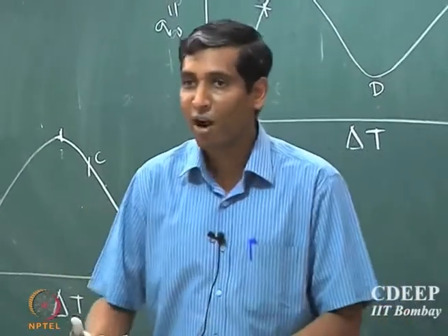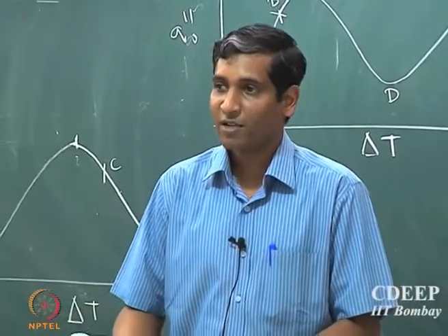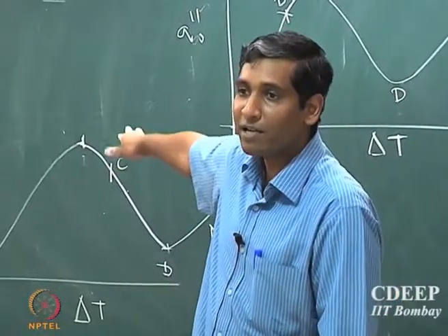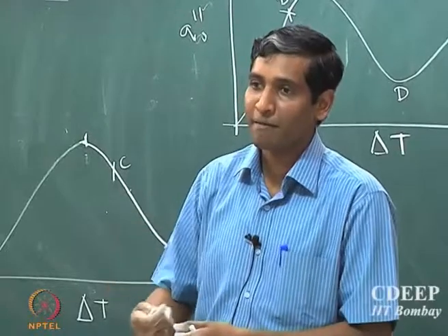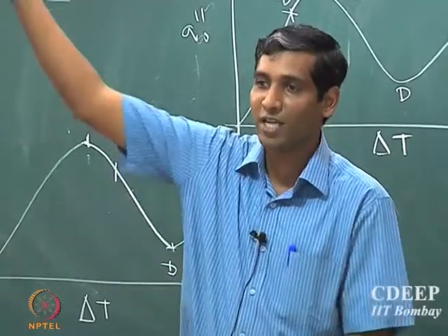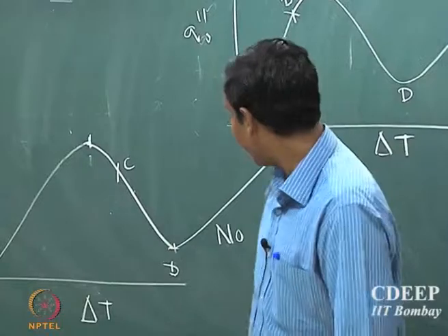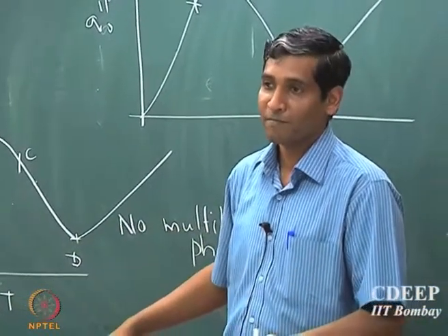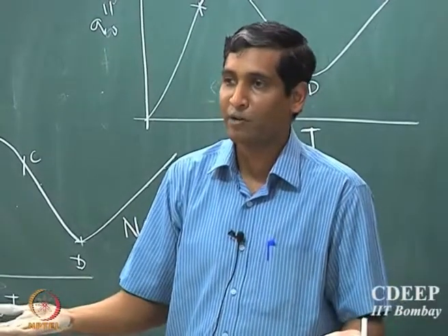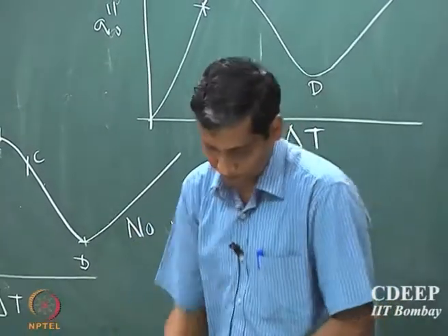Until all the fluid is heated and converted into vapor phase, the fluid will continue to be at Tsat temperature. Only the local vapor temperature will go above Tsat, but the vapor is going to escape and go away. So the liquid continues to be at Tsat. It will continue to be at the boiling point till all the liquid has escaped into the vapor phase.